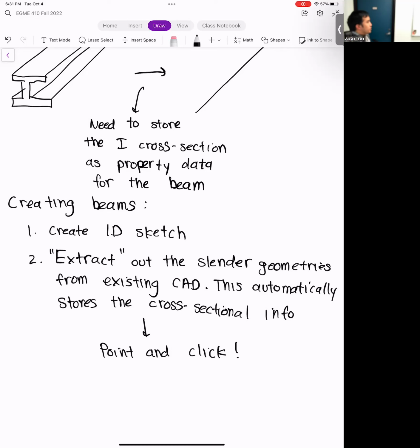So beyond that, there's not much to say about beams. Compared to shells, they're a lot easier to use, and computationally they're extremely efficient because a 1D element at most is going to have 3 nodes if it's quadratic. And for a 3-node quadratic, you're getting all this accuracy, and it's really nice.